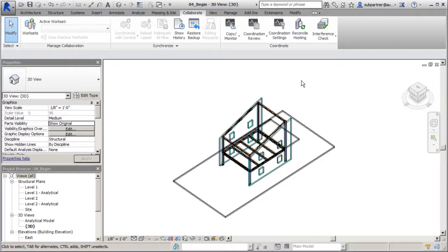So let's bring in some other elements that we can't see. You remember earlier when we tried to bring this model in, we were missing parts, and we messed around with material to get those exposed. Well, what if I want to see the actual architectural elements and I don't just want to see structure? I want to make decisions and run analysis on my structure while also knowing what's going on architecturally. I can easily work around that with my visibility graphics. A good example is if we wanted to have the roof in place, or maybe see the windows and the railing. Now, I'm not too concerned about the windows and the railing. The openings are good enough for me, and I know the railing is going to go around the perimeter, but I might want to know what's going on with that roof, especially since we're applying loads.